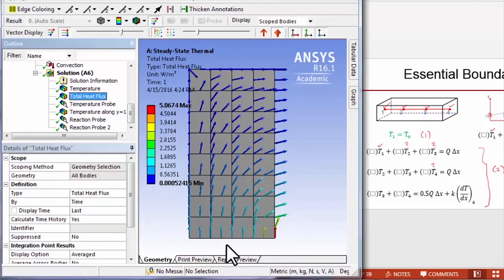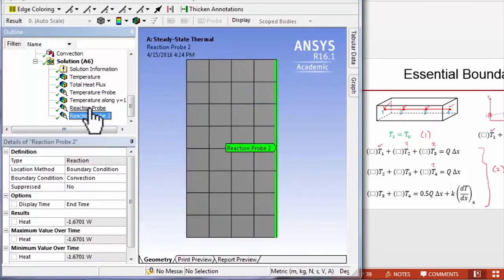Under the heat flux vector, you have heat coming in, heat going out, there's no heat crossing the other two boundaries, and there's no heat generation. So this has to balance that, and if I look at that value, that balances the heat coming in. So that's a check on the aggregate energy balance. We saw that doesn't mean that energy is conserved for each infinitesimal element, or for each finite element. It just means that it's conserved in aggregate. But that's a very important check to do.